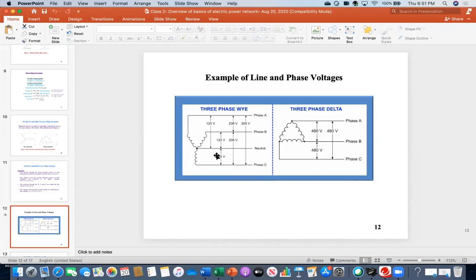So, could you follow me? Now look at this on the right side. Between two phases, right? Sorry? What did you say? Phase voltage between two phases. So what I am telling is that line to line voltage is √3 times the phase to neutral voltage, or the phase voltage. Okay, yes.